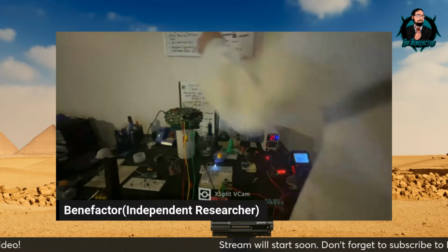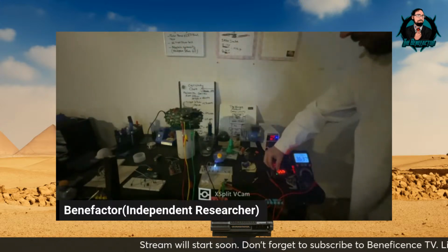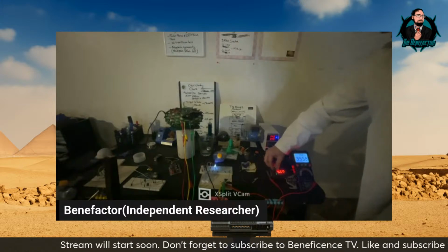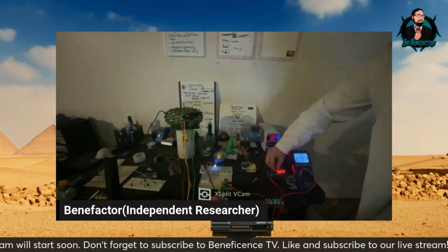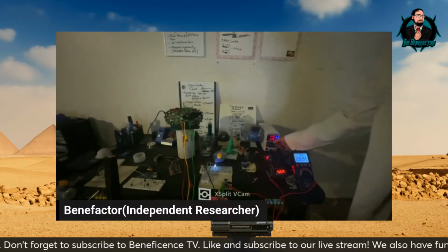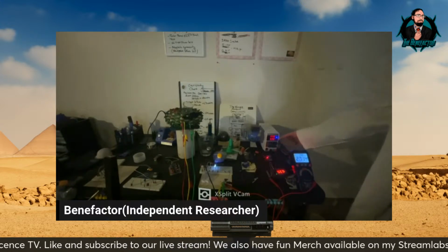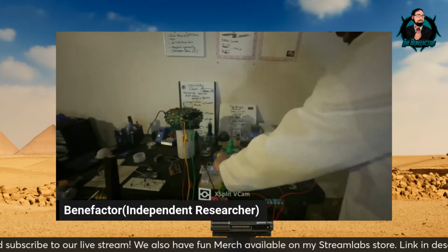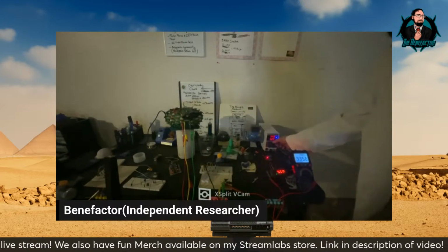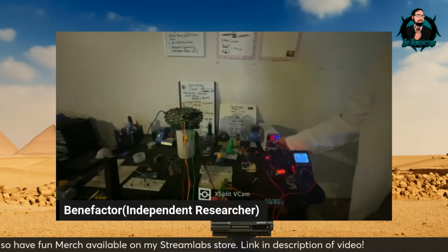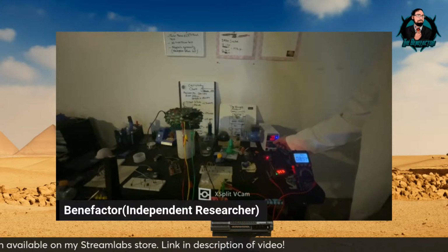Okay. So you said bring the duty down to 30. Yeah, don't go over 50, Ben, because then you're distorting the signal, I think. Or you're just overcharging the coil. It only takes so long for the coil to charge up. You don't want to keep charging it after it's charged already. That's the duty cycle right there. So you've got to figure out how long it takes for that coil to charge up.